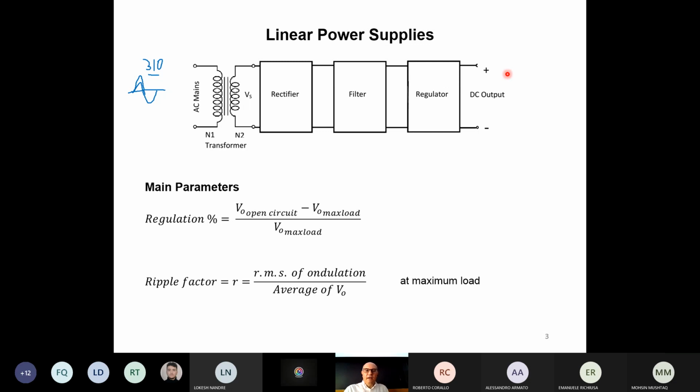Okay, so if I consider it, I don't know if this works. Let me show if it works. Control, fine. If I suppose that basically we will have a resistor placed here, something like this, okay? It's a touch screen. So we usually call it RL, load resistance. When we apply a load resistance to our power supply, we will see that there will be some current flowing through the resistor. Due to this current, usually the output voltage will go down, will reduce, because we are loading the power supply.